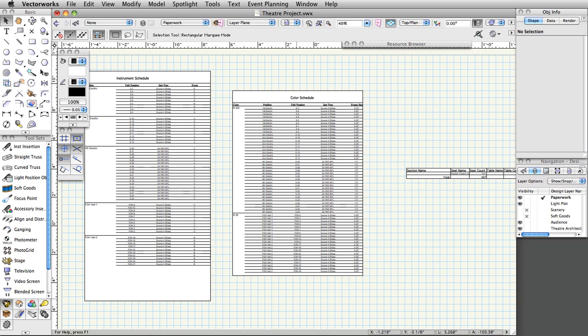The Create Plot and Model View command will create a definition layer and model layer for the selected positions. The selected positions will be moved to a definition layer and replaced with a design layer viewport. A second design layer viewport will be placed on the model layer. This allows you to rotate the design layer viewport on the model layer so the vertical positions appear correct in 3D views. Switch to the light plot layer.